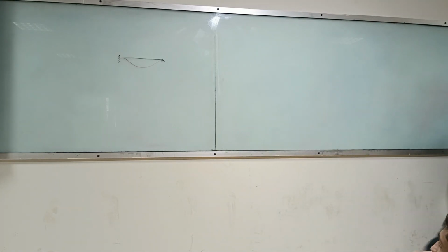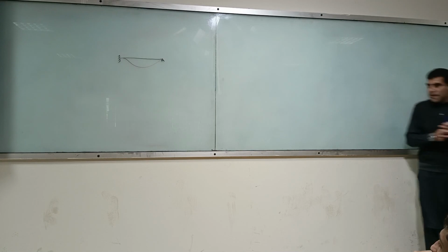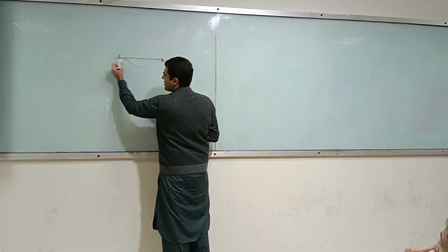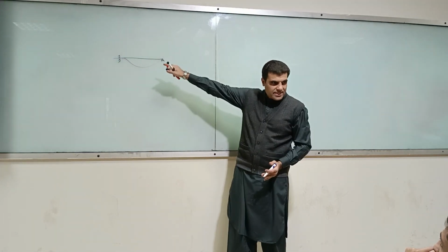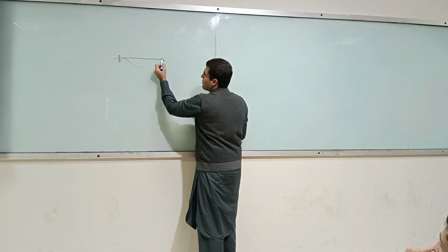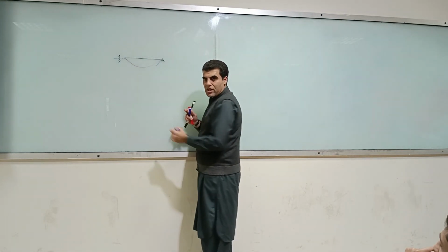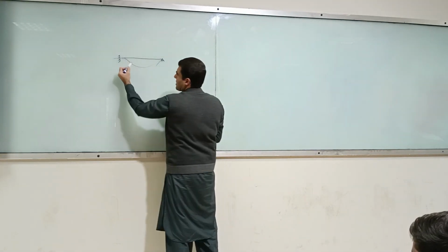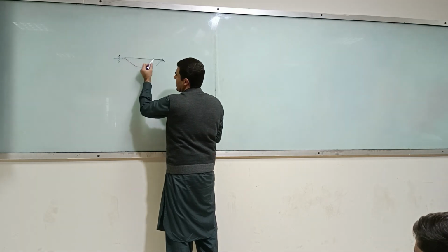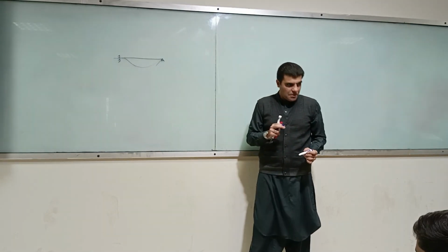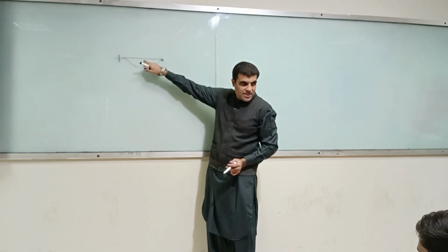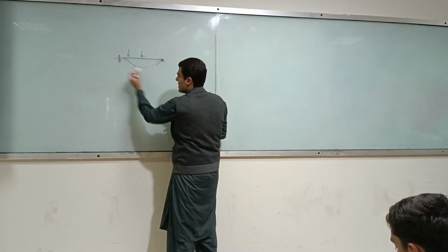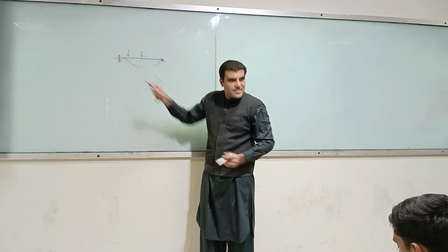Yes? So what I am saying is that rotation over here is 0. Why? Because if I draw a tangent, that tangent doesn't move. It stays at the same point, isn't it? Yes. However, over here I have got some finite rotation. This is the rotation. What do I mean by rotation? How much this deformed curve makes with the original axis of the beam. This is the original axis. The black is the original axis. When you apply load on it, any sort of load, it will assume a profile, this sort of profile. Do you understand? This is the deformed profile.